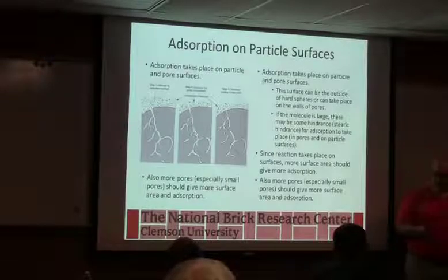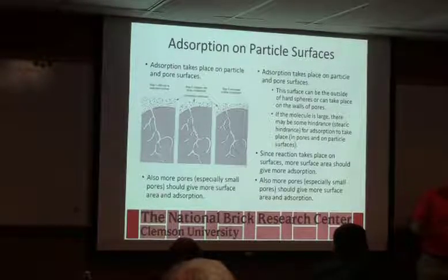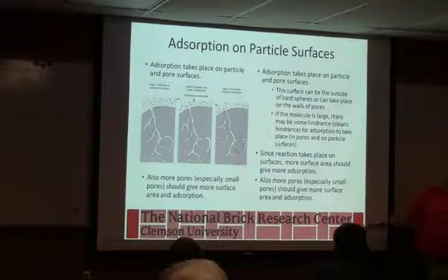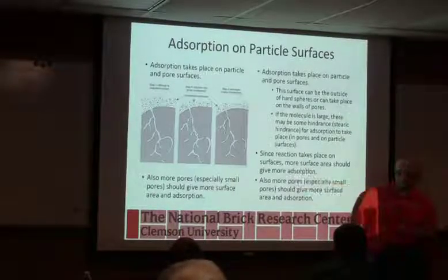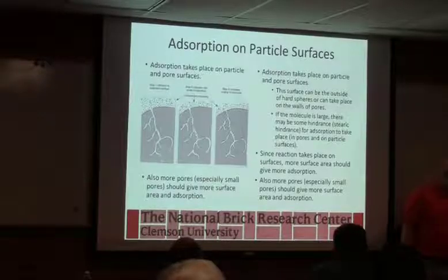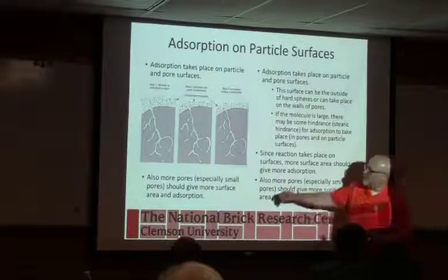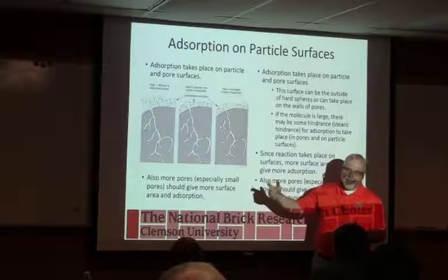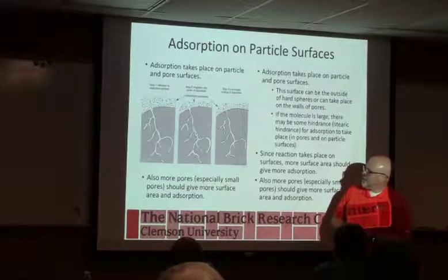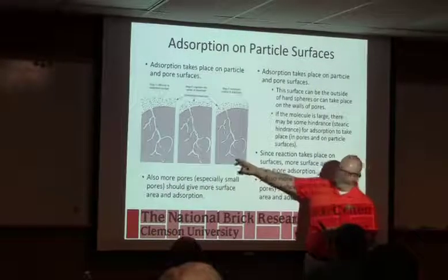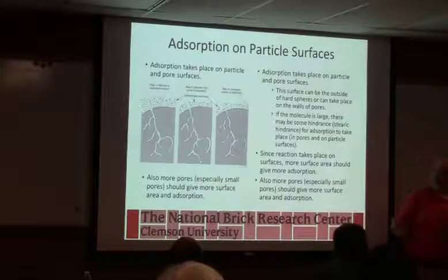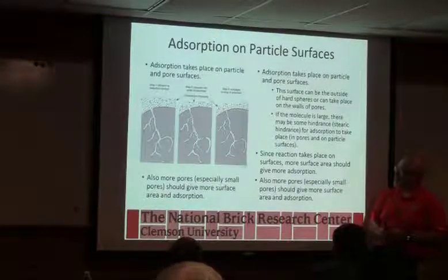So if we get limestone, there's a whole range of it. You can get marble chips, okay? They have essentially no porosity, and they tend to be not as good as scrubber reagent. The best one I've ever found is actually a fossilized coral. There's a bed of it in coastal South Carolina. It has a very high surface area, and it'll pick up more fluorine than anything else we've worked with, because we've actually done a lot of these kind of tests.